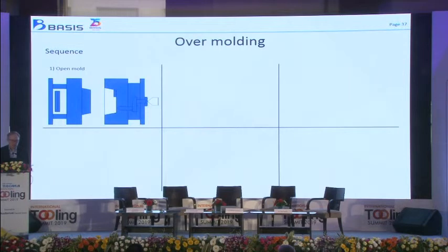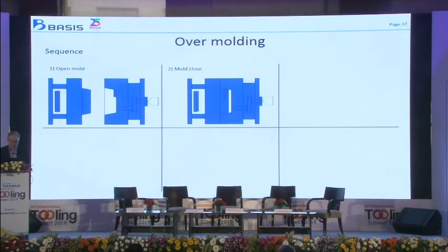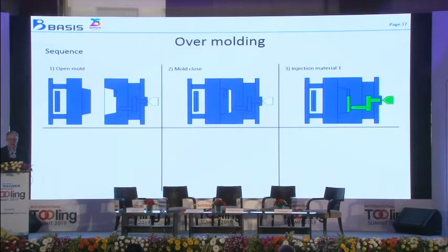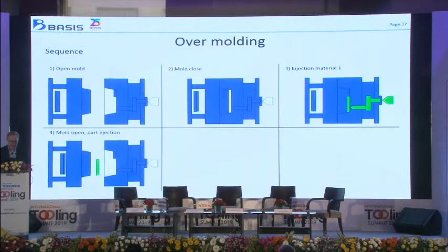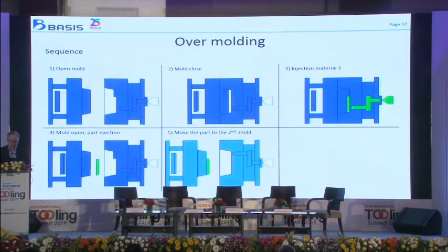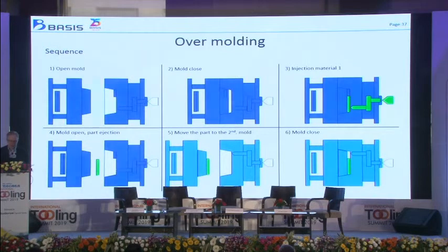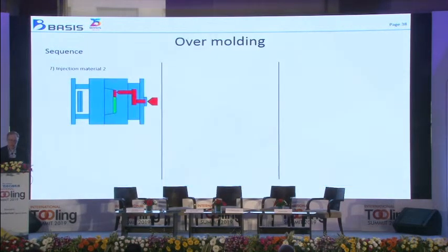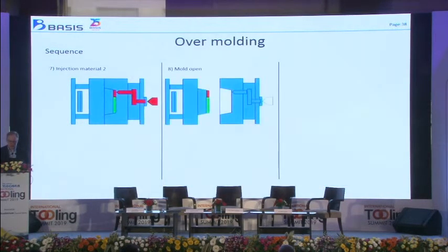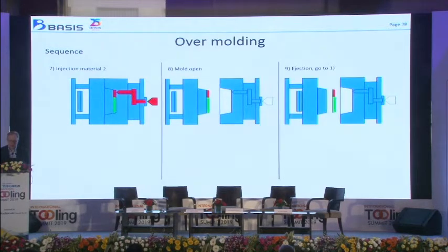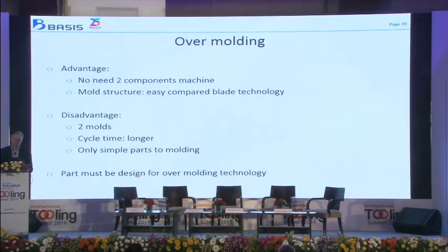Here the sketch of the mold, one cavity mold. Mold open, mold close, injection of first material, mold open, part ejection, transfer to the second mold, close, injection of the second material, open, and ejection. In the meantime, we can restart.